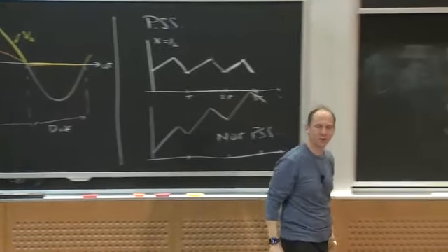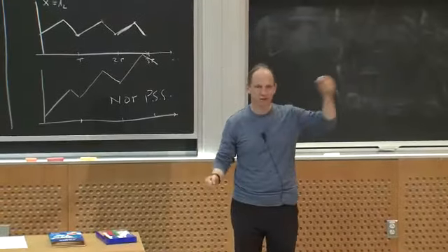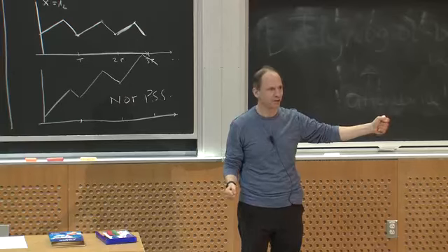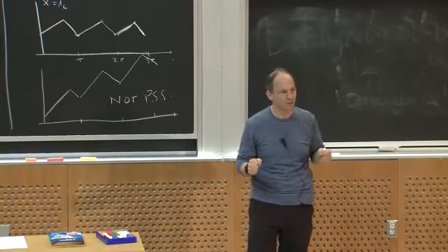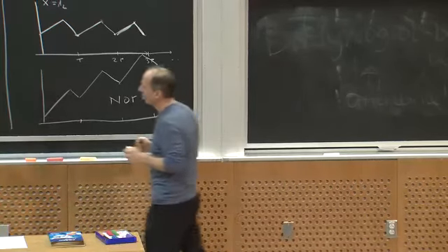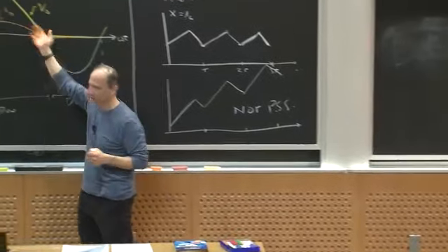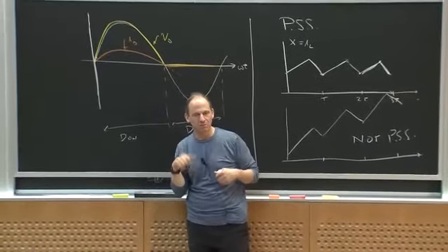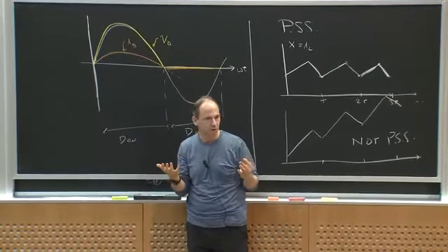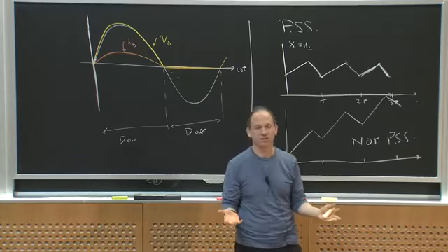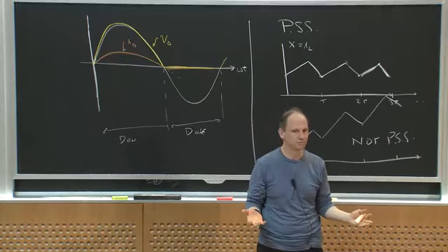That's why I would use a switch. I've now taken AC and turned it into DC. You can't do that with a linear circuit element, right? But a diode you can use to do that. So I might use this if I had some AC voltage and I wanted an output with a DC component to it. Or what I merely might want is a constant DC output, right?